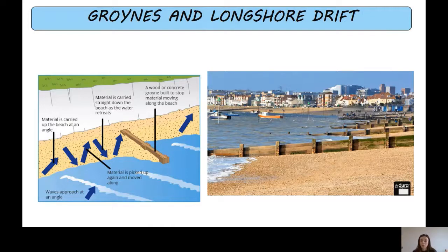But groins, that's human interference there, groins can impact the equilibrium of the sediment cell because the groins reduce or halt the sediment supply to the sink region. So groins only benefit the area directly where there are groins, directly where it stops longshore drift. But it does mean it hinders the supply of sand further along the coast, which will only increase the rate of erosion.